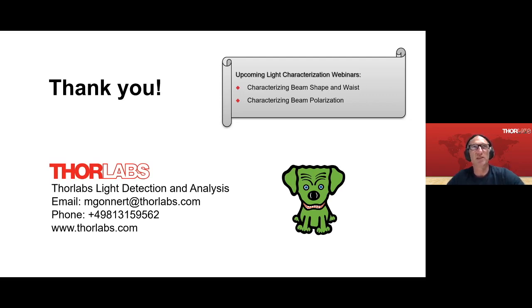We calibrate spectrally with a monochromator, and here the limit is the output beam size of this monochromator, which is in the 1.5 millimeter range. So every photodiode with an active area larger than or equal to 2 millimeters can be calibrated.